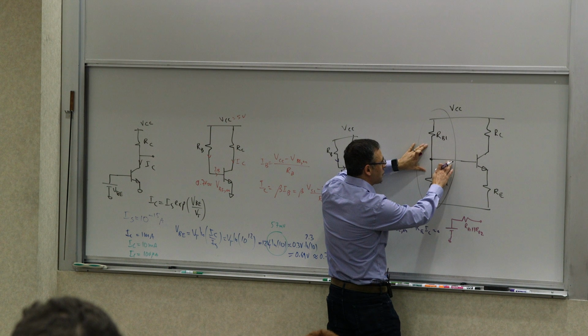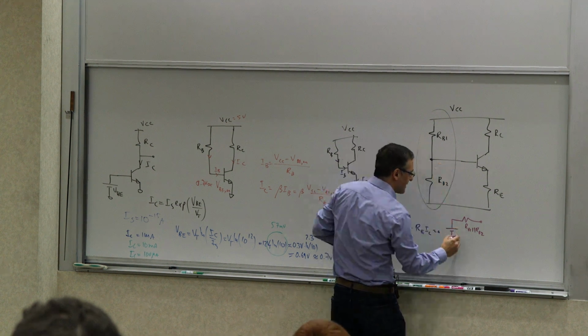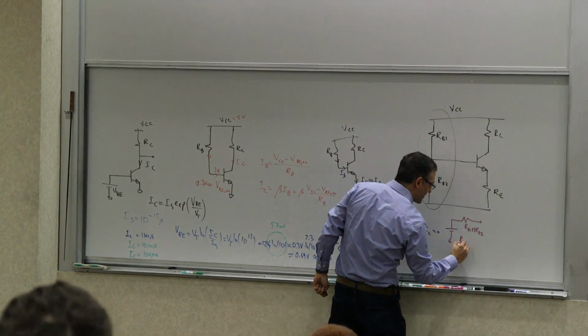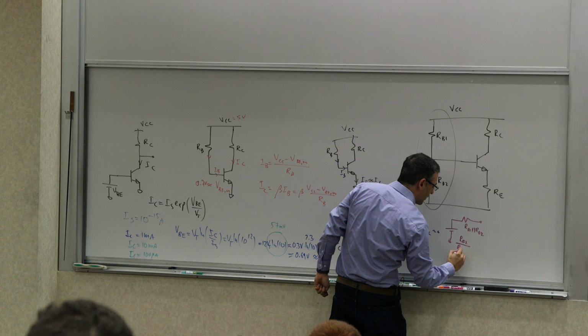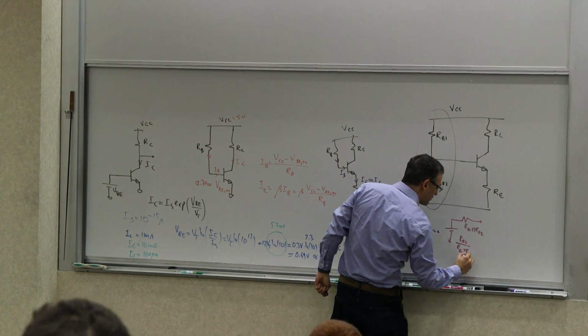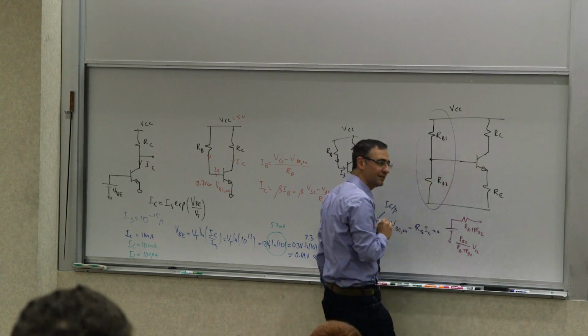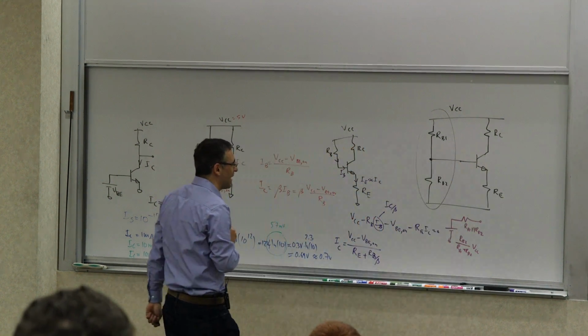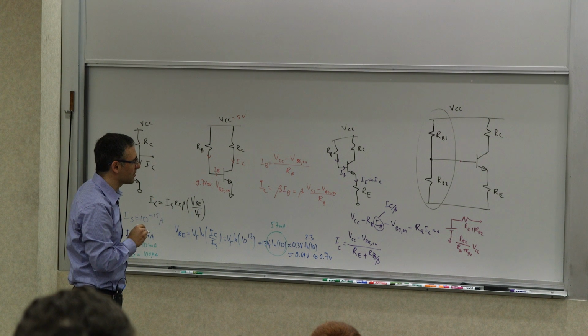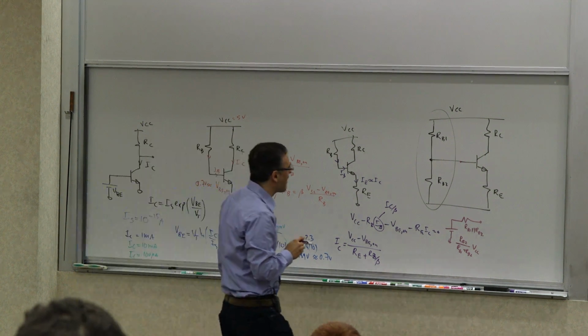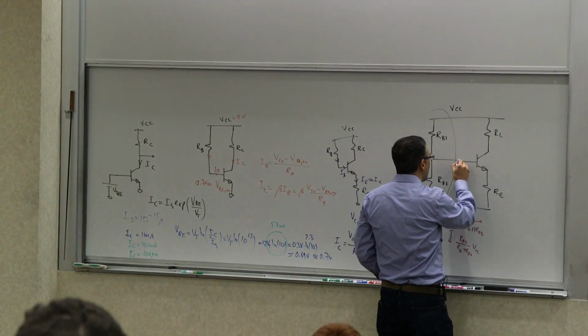And what is the voltage that you will see when you draw no current? It's the division ratio times VCC, RB2 divided by RB1 plus RB2 times VCC. So it's as if you've connected that equivalent to the base, like that purple circuit, or magenta, whatever that color is.